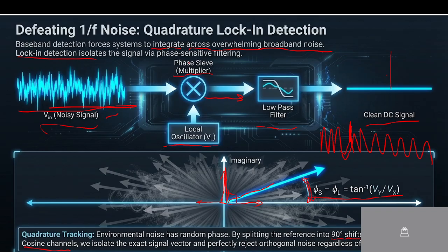So here, first of all, the amplitude, the responsivity, is R = sqrt(Vx² + Vy²), and theta, which means the phase, will be tan inverse of Vy upon Vx. This is what is written here, the shift, or you can say delta t, delta phi or delta theta also.